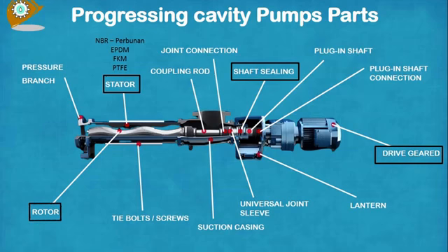Depending on the work environment, they are made of annealed alloy carbon steel plated on the outside with a 0.3 to 0.4 mm layer of hard chrome. For highly corrosive and aggressive environments, rotors are made of stainless steel, also plated with hard chrome on the outside.